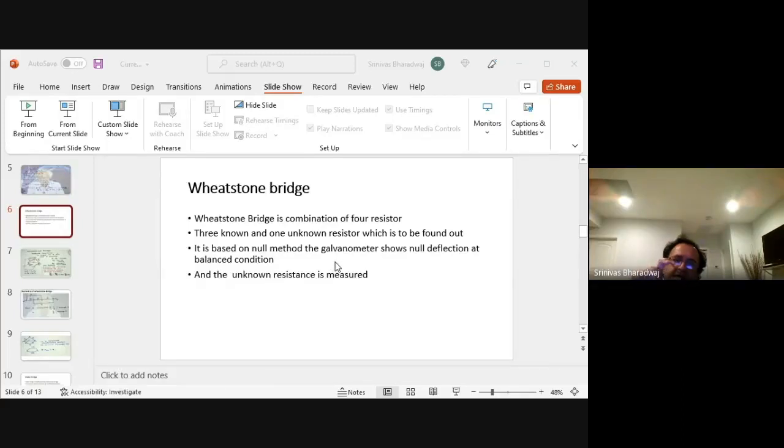It is a device whose resistance you can vary in such a way that there is no current. So by varying this resistance, you are changing the length, so there is this length plus this length, which leads to the net resistance, such that this whole branch does not have any current.